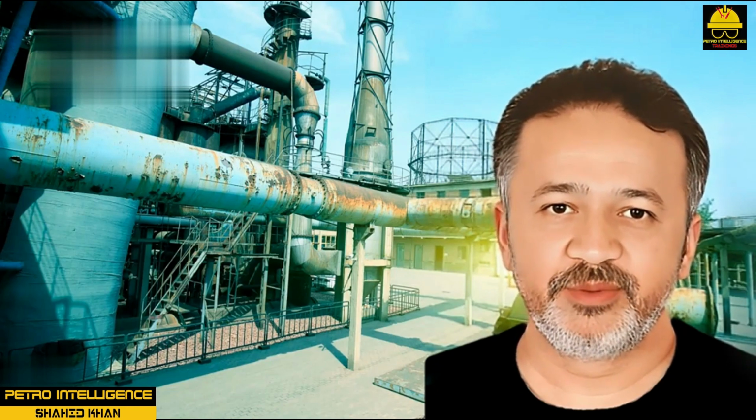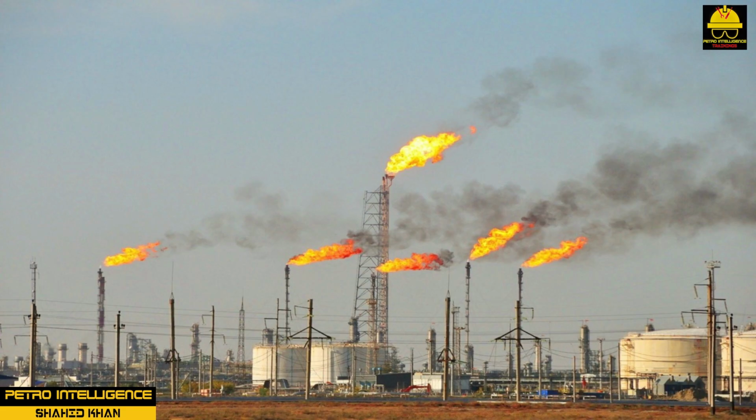Flare stacks are provided to burn vent and waste gas from the units. Normally the waste gases are burned as fuel gas, but at times when a unit upset occurs, large quantities of gas must be disposed of at low pressure to the flare. The flare burners and piping are designed to handle these flows. They must burn the waste gas with a minimum amount of smoke and must be high enough so that the surrounding area and its equipment are not endangered by flame, heat radiation, and fumes.